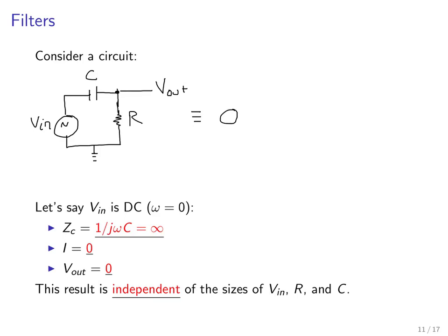as the following circuit. We have V in again here, but then we have the impedance of the capacitor, Z sub C, we'll call that. Then we extract V out up top, and we have Z sub R, or just R, of the resistor. When we look at this in terms of impedances, remember that impedances allow us to treat any circuit element like it's a resistor. So you might recognize that this circuit looks an awful lot like a voltage divider.